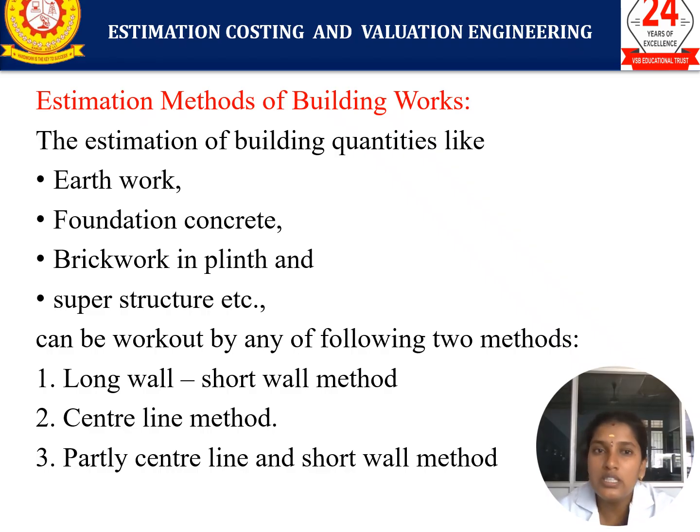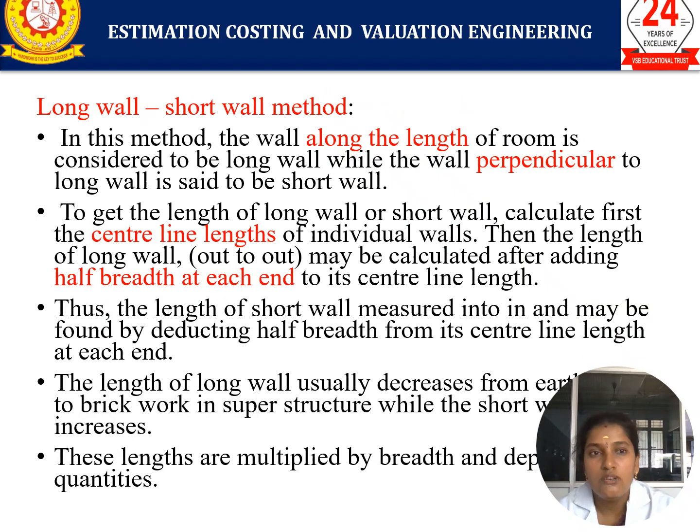What are all the methods we are going to adopt? First one is the long wall and short wall method. Second one is the center line method, and partially center line and partially long wall and short wall method. So these are all the methods to be adopted for calculating this estimation, right? We will see one by one. First method is long wall and short wall.